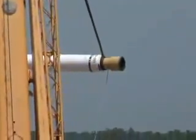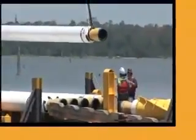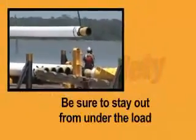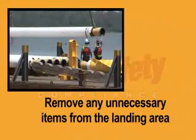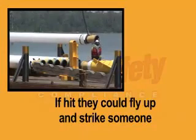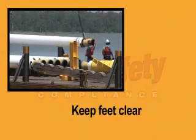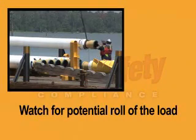Landing the load safely is the last step to the lift. To assure a safe landing, follow these steps. Be sure to stay out from under the load. Remove any unnecessary items from the landing area. If hit, they could fly up and strike someone. Keep feet clear. Watch for potential roll of the load.